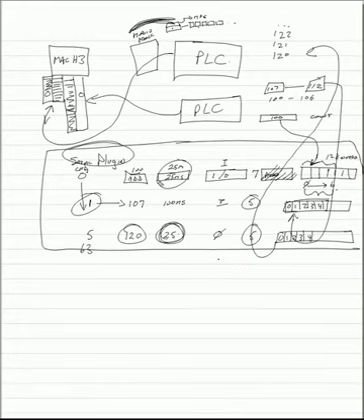If you have an MPG and your PLC is capable of keeping a simple count, you can use the brain to send the MPG data through your brain into Mach 3's count register and use an MPG with almost any PLC. All right, I hope this helped. I know it's a bit confusing, but I imagine it will all come together in time. Thanks.